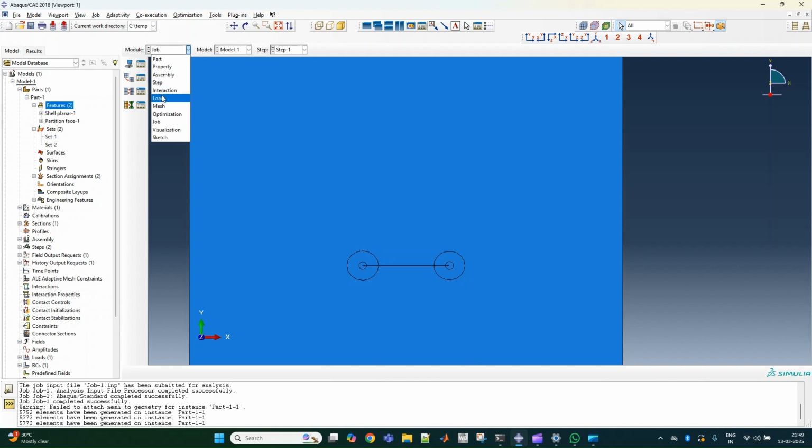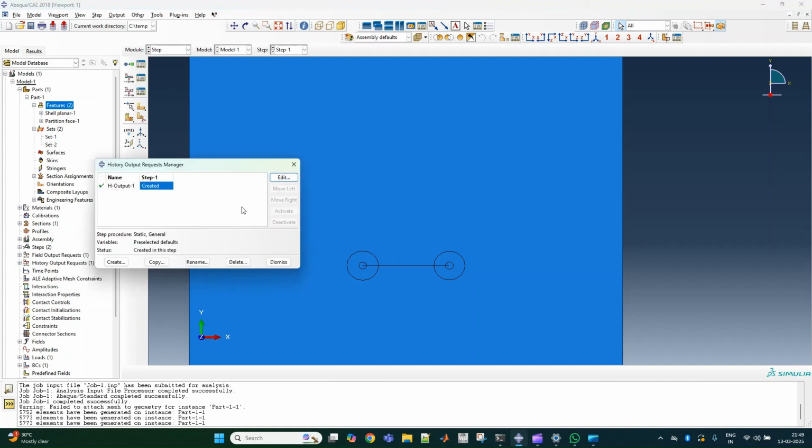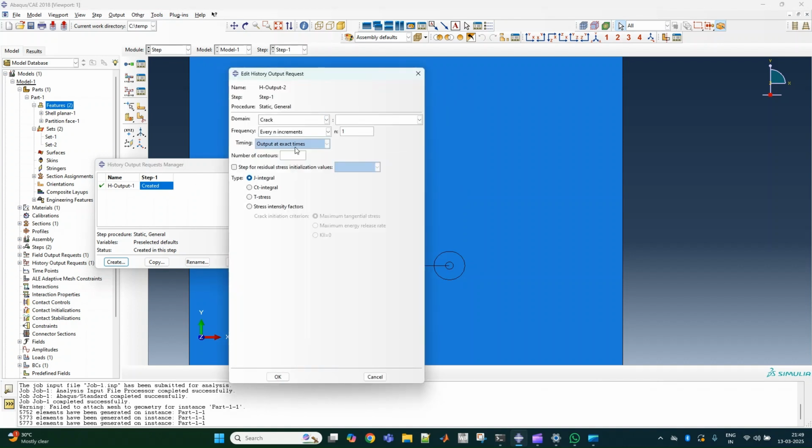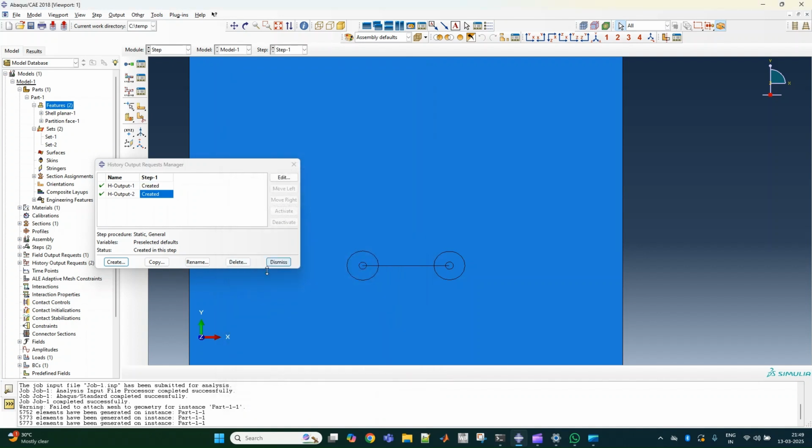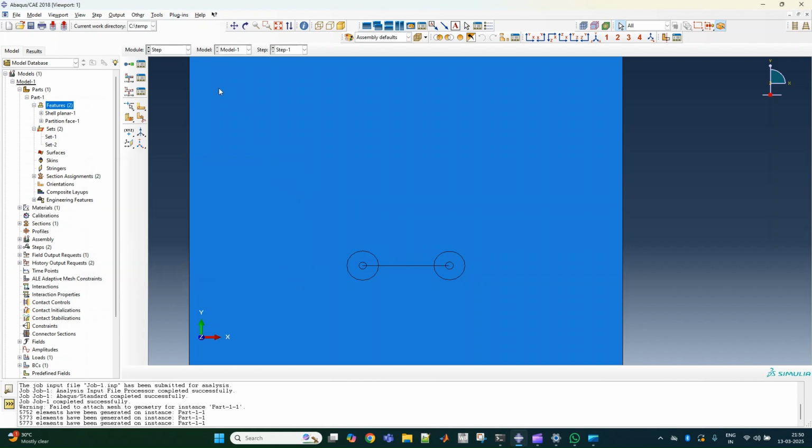We'll just get a value for that. For that, we have to go here. We'll stay in output. We'll create a new request. We can create a new request, or else you can. Okay, let us do it by creating a new request. Go to the track, and track is track 2. Here itself, we could have given another request in the previous one, but then we'll do it. In this case, we'll do it for 5 contours and just stress intensity factor. Let's see this rate. We are trying now. Then we see that these are almost same. These are expected to be almost same.